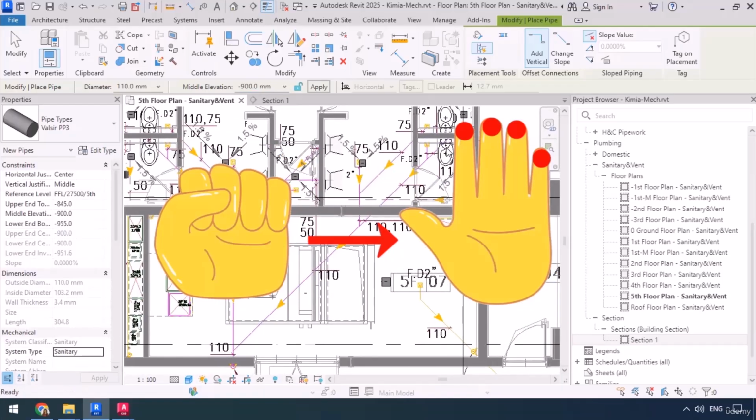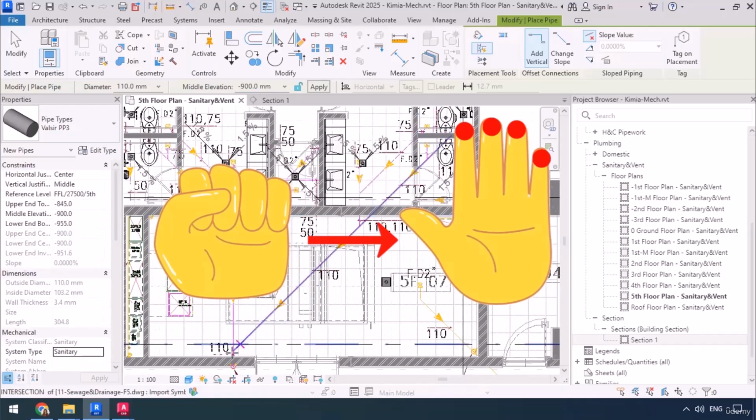And also, this pipe is going to be drawn from the fixture leading to the riser. So I'm going to put it into a code for myself, as in I'm getting farther from the fixture. This going farther has a negative connotation to it, so the pipe slope is also going to be down. Negative or down slope by 1%.